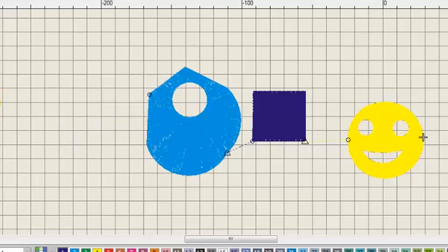Now, our input A tool is used generally for columns of satin stitch. Now, because it's satin stitch, you don't want the columns to be wider than sort of 7, maybe 8 millimeters. But the beauty of this tool is that you can vary the width of the column. So I've selected my stitch type, I've selected my tool, and let me select the color. So I'll select the color orange.